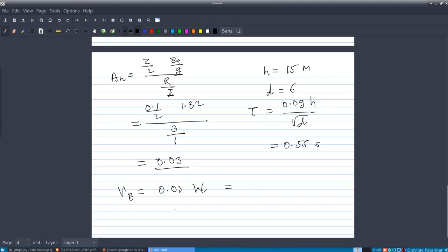So most of the important part that was required from seismic analysis was done here. We have base shear. Now the next task is to distribute that base shear at different floors, so that for those particular forces, I can find out what the internal forces are, and I can continue my analysis and then continue with the design. So that is achieved. That is also given in the IS code here.